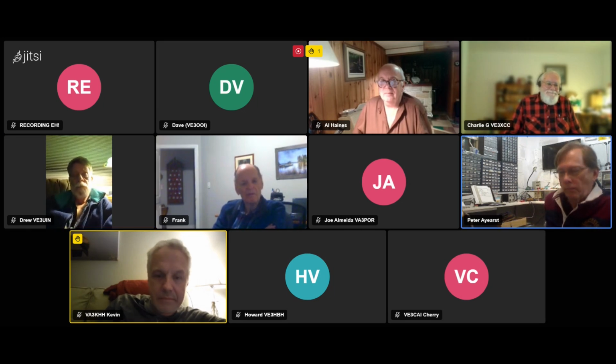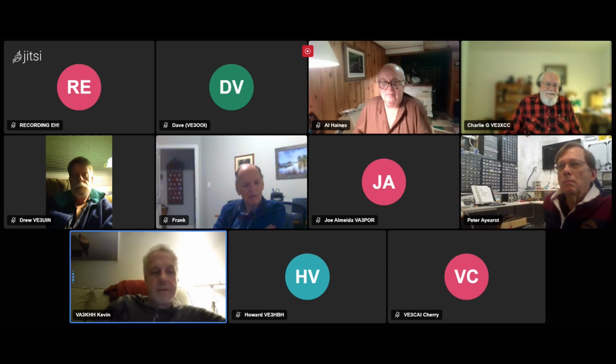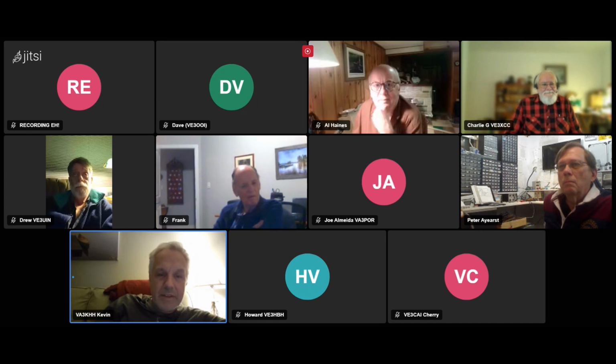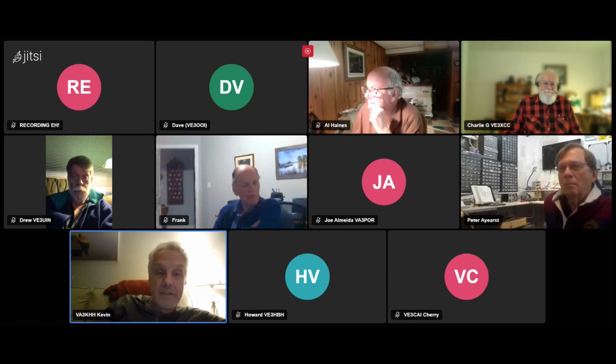Kevin, you're up next. Hang on, I'm muted. Okay. I was looking up when you were talking about the power rating of the 174 cable, and the difference between some of the less quality manufacturers and something like a Belden. Belden handles over 200 watts at 30 megahertz on RG174, and it's rated for 1100 volts.